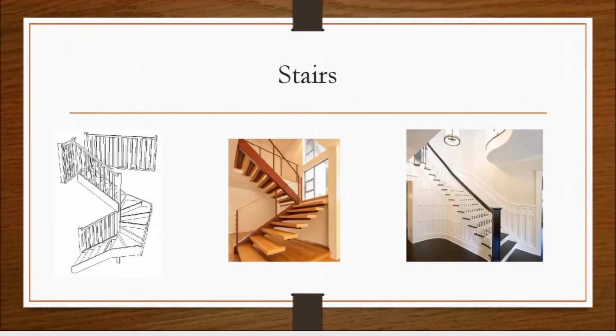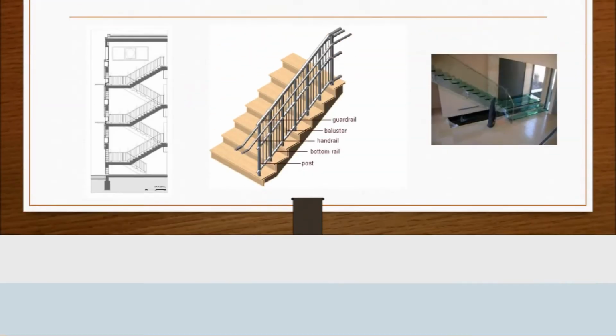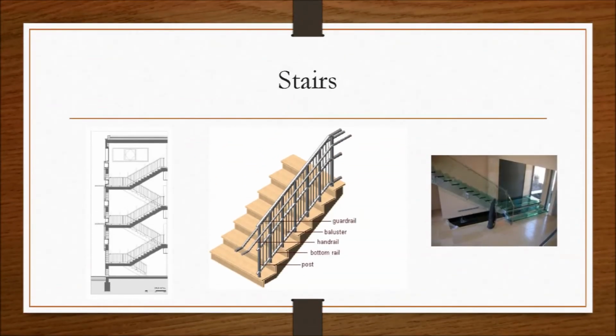Stairs. Building codes may allow limited use of curved, winder, spiral, switchback, and alternating tread stairs. This depends on the occupancy classifications, number of occupants, use of stairs, and the dimension of the treads. Most stairs must have a clear minimum width of 44 inches. With an occupant load of less than 50 people, a 36-inch minimum width is permitted.